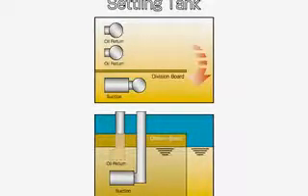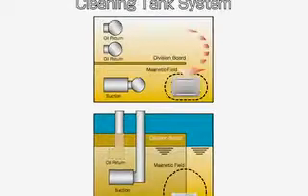First, a separator plate is added to separate the oil return and suction portions into the end of the tank. Also, the oil return pipes will be collected at one location. This configuration prevents the oil from being mixed, and allows it to flow without agitation, thereby making it easier for the sludge to coagulate and to precipitate to the bottom.